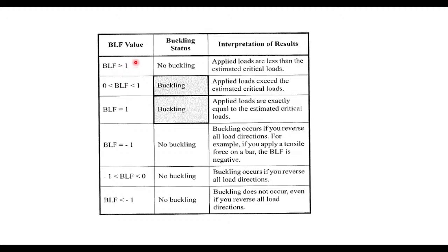Now, a very important thing is you should not take only 1 as a reference. Sometimes, as per the factor of safety, some components will have a buckling load criterion that should be 4, or 4.5, or 6, or 2.5, or 3.2, depending.